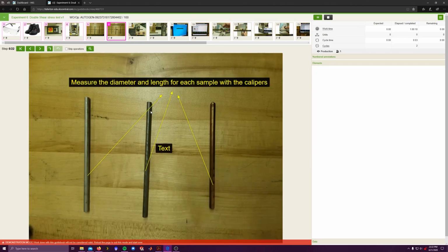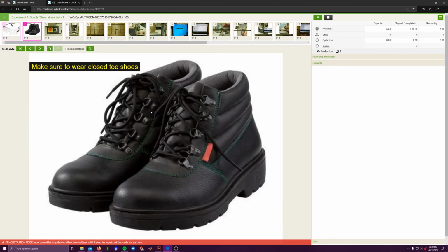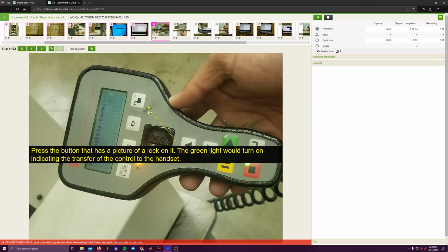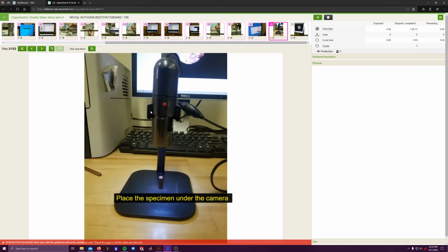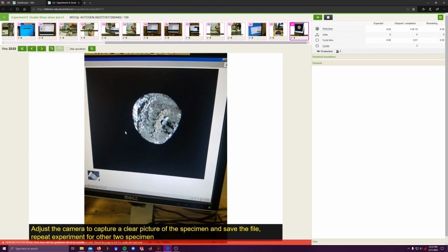What you would see if you had copper, I went right past it. Okay, so if you had copper, you see this kind of smearing here. This would be over the majority of this surface here because copper is much more ductile than something like steel. So you should have pictures in the provided data as well. And basically you're going to comment on the fracture appearance for each of these metals and kind of explain why they look the way they do.